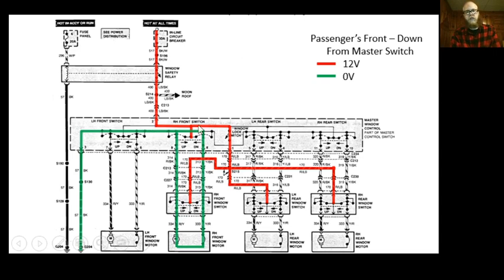And then the interesting thing is I've got this 170 circuit over here, and this supplies power to each of the individual window switches, so if I want to control the window from there, then I can grab power at that middle pole at that point. So, neutral, I want to roll down. Hey, it worked just like the driver's window did, because we're only using the master switch. Master switch has power, so it supplies the power to the window motor, and it also is the pathway to ground. So we flow that way. Now I want to go the opposite direction, neutral, and then I hit the switch, and now current flows in the opposite direction.